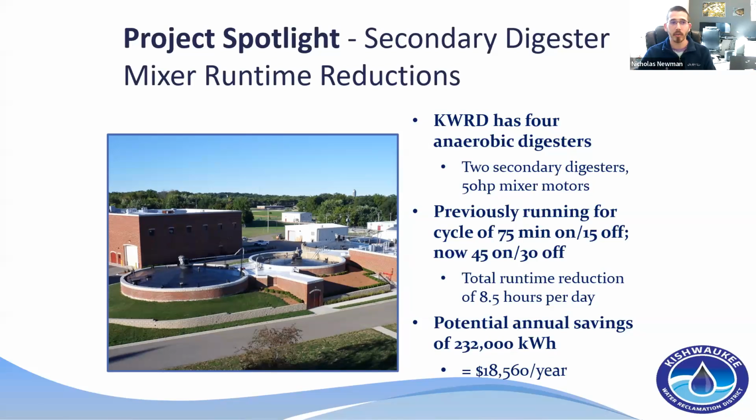After doing some investigation and making incremental changes, we discovered we were running it way more than we needed to. At the point we're at now, which is getting close to the bottom threshold of where we feel comfortable making changes, we're running them on a cycle of 45 minutes of active mix time and 30 minutes off, which calculated out is 8.5 hours less mixing per day, which is pretty huge.